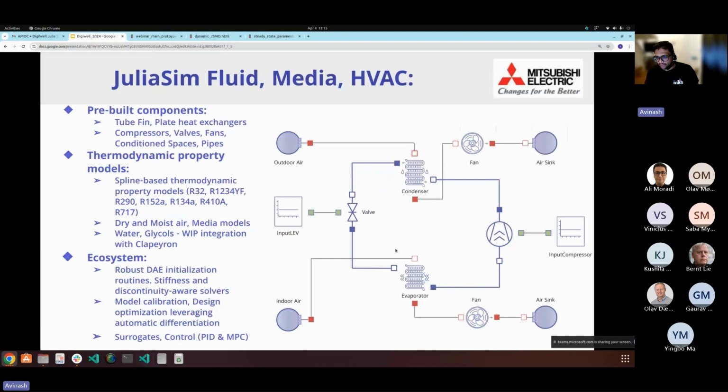So one would have the evaporator, which is the part inside the room in which heat is removed from the room to cool the room. So evaporation, so cooling by evaporation, and then the refrigerant is compressed to a higher pressure, and heat is lost to the environment, and then there's a valve. And so this is the simplest example. One can have more complicated variants of these.